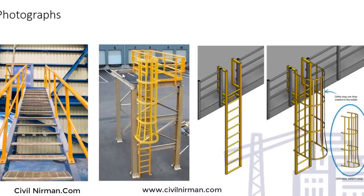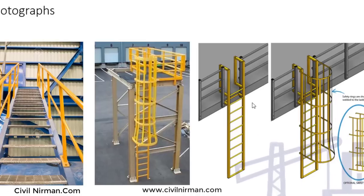Here you can see a small platform with a caged ladder. Now, over here, you can see the cage, and in the next picture, it's a platform with access by ladder without providing a cage. So what's the difference? Why in one picture can you see a cage and in another there is nothing? Well, it varies with the height of the ladder. To provide extra safety to a climber, a cage is provided.